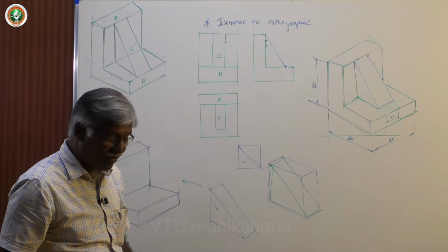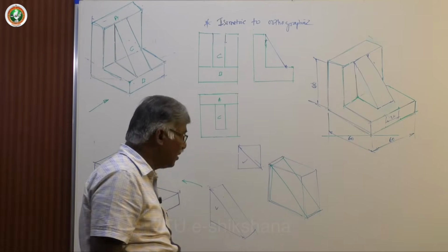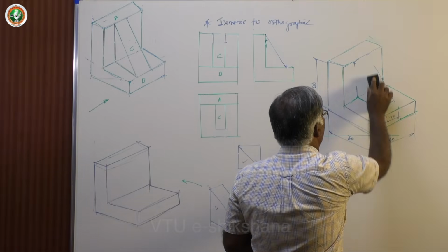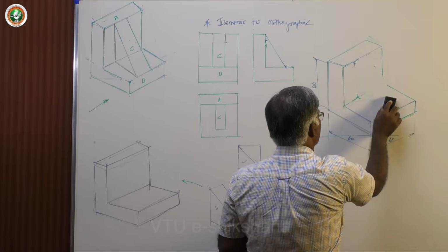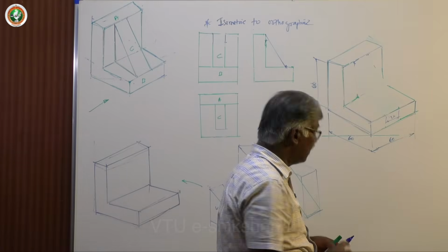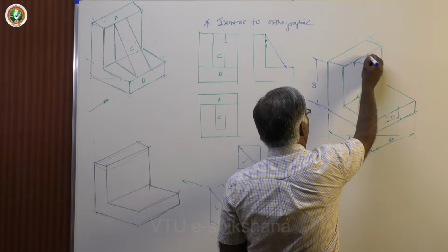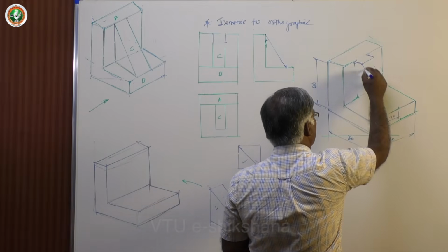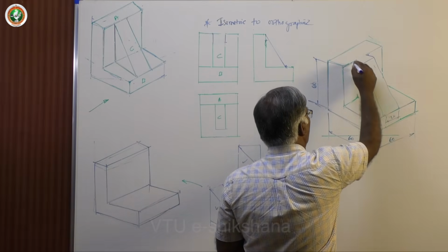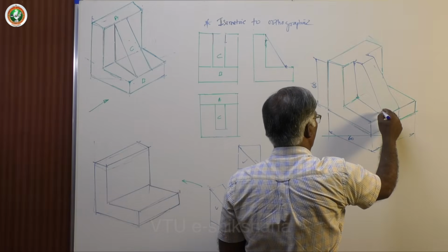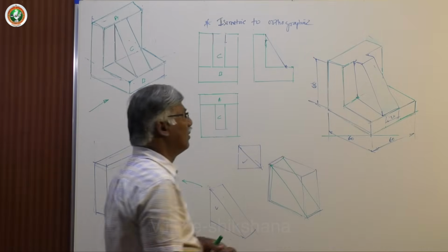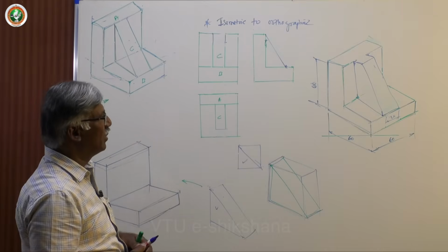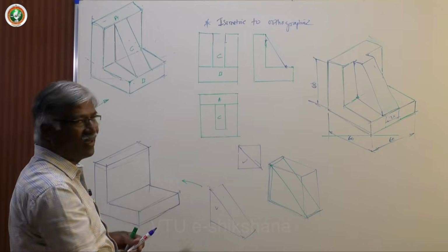Now let me have some more changes, little special changes here. Extend the top face by some value, 10 mm, and join this here. This is a different type of web. This is for supporting some machine components. Okay. This is another different solid now.